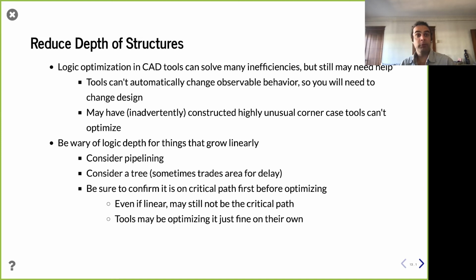And so, one place where delay can really grow very big, right? A lot of times delay is intrinsic, you do certain operations and it's hard to fix, but that's only when you've been optimizing for a while, right? When you're first looking at your first timing report, you're going to see some long delay paths that are trivial and you should go fix, right? Some of those would be things where the logic depth seems to grow linearly, right? In the examples we've seen so far in this course, you see me do a lot of things with recursion or for loops, where we build things like our own pipeline shift register. We did those linearly because that's what we were just trying to do, and we didn't really think about it. Remember we use foldLeft, for example, which could be linear depending on how we use it, right?